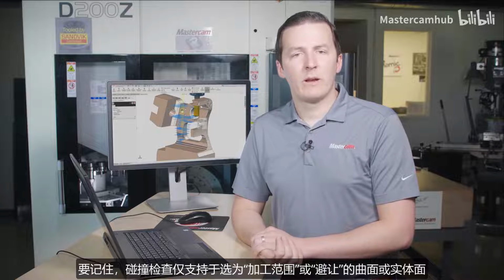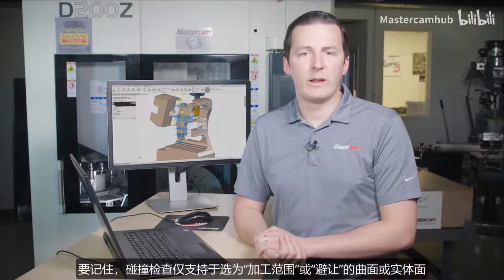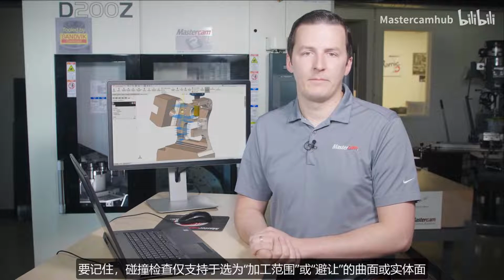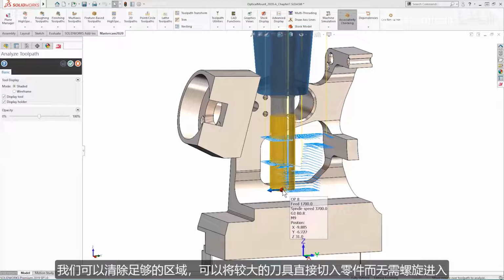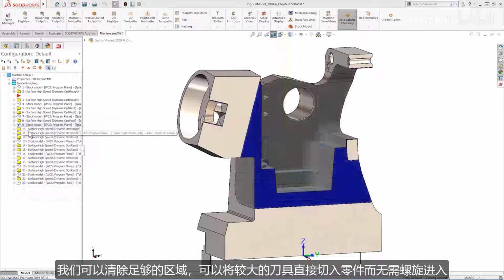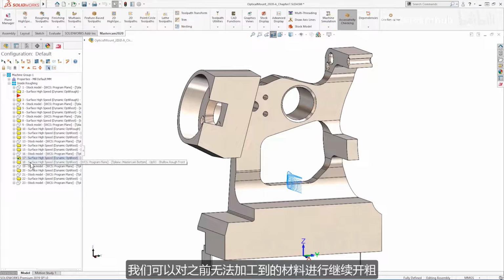It's important to remember that collision checking is only performed on surfaces or solid faces that are selected as machining or avoidance geometry. By repeating this process in all 6 of the part's openings, we can clear out enough material to drop the larger tool into the part without a helical entry. And by creating stock models and rest roughing toolpaths, we can then rough out the material that we could not reach before.